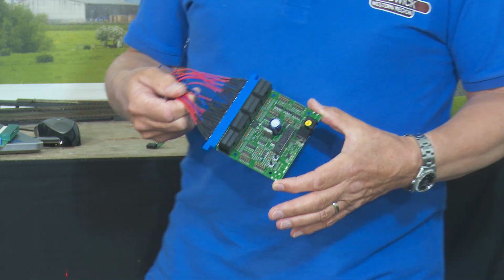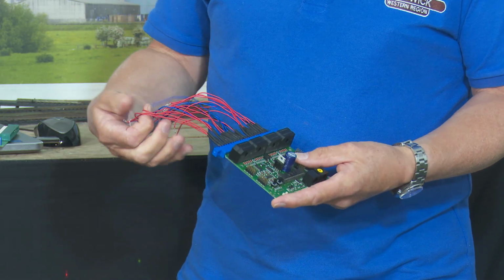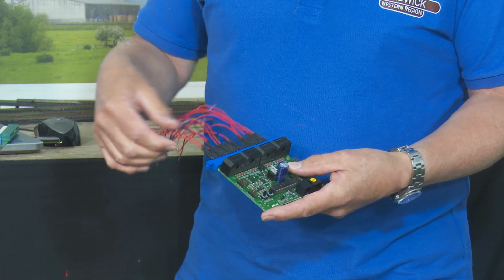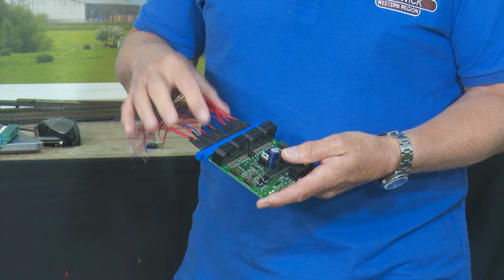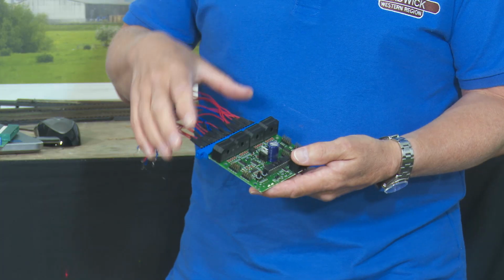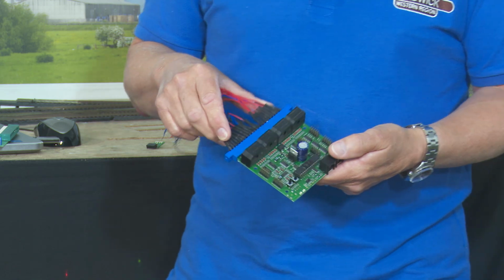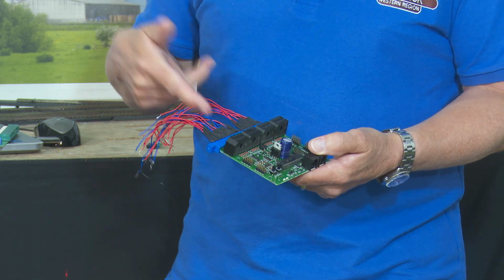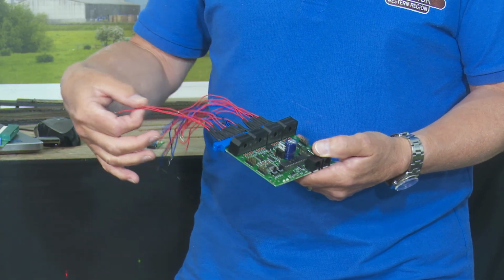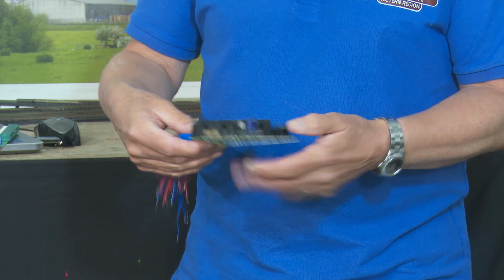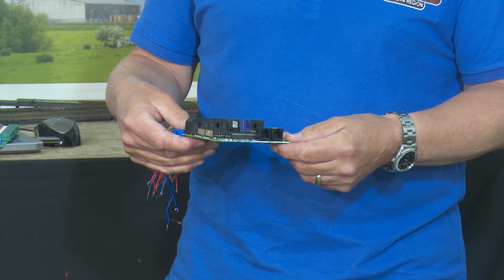Now this is a BDL 168 made by Digitrax, and as you can see, these red cables are the ones that go off to the red rails, and there's also a couple of cables for power in just to run the base of the board, which is between 12 and 18 volts AC or DC. Also you have the power going in from your red bus, as it were, that then gets split into these 16 feeds that go out. There's also a Loconet cable in and out where you daisy chain Loconet across.